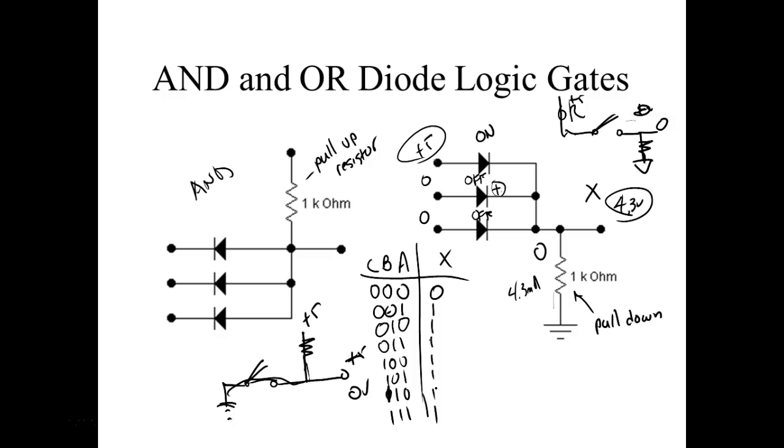That's right. Over here, my anode is pointing toward the positive, and on an OR gate, so over here, any 0 will turn this guy here on. But the problem is, if it turns it on over here, that's going to bring that 0, if the diode is perfect, and put it right there. If I didn't have that pull-up resistor there, what would happen? We'd have a short circuit, right? Does that make sense?